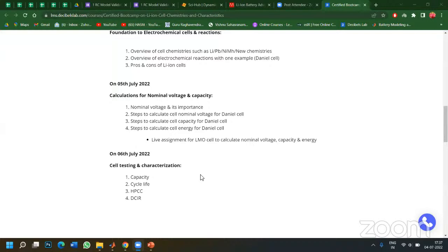Let's say we have a cell, or we're going to build a cell. How do we ensure that we get the data from the cell? So the data is basically, okay, I'm targeting about 2000 mAh for a cell, but do I have 2000 mAh at a given available discharge current? Do I have it at available discharge temperatures? How exactly do these curves come? Okay, so we would look at some interesting details on some specific cell chemistries.